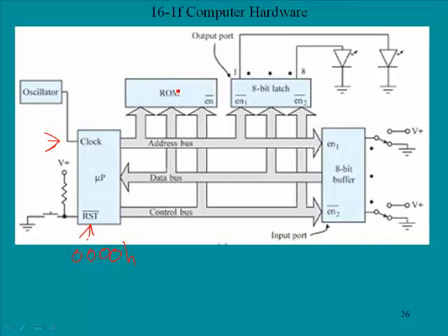So here we have a ROM chip, and typically when a PC starts up, it will go to a very specific address. It's usually not this one, by the way, but we're using this one for our purposes. It will go to a very specific address and begin reading information from ROM, and this is fed into the microprocessor, and the microprocessor will execute, for example, the power-on self-test. That's not an issue for this course, but it will start the computer, and when it finishes this POST program, it will call the operating system, and then the operating system starts up.